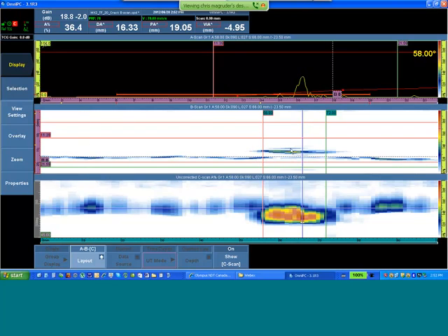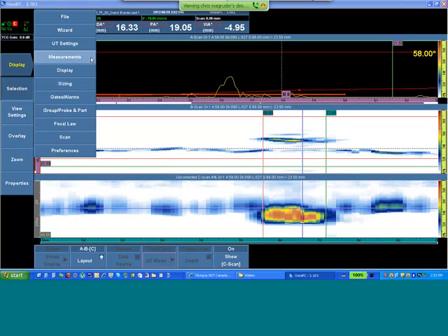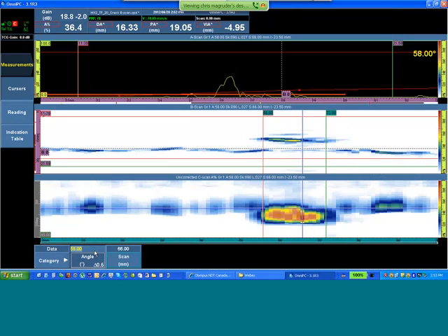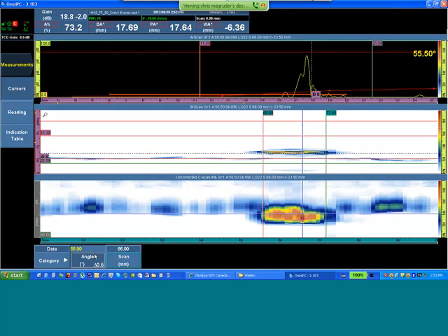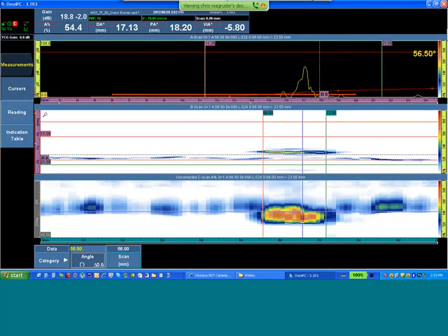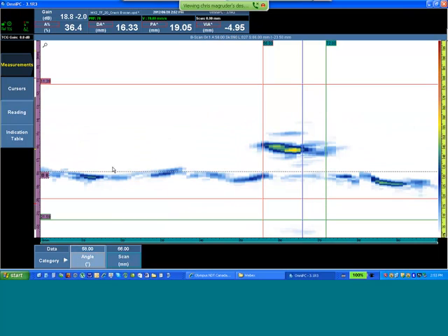So I can see my length sizing and individual different tip facets of the crack from a side view. So menu, measurement, cursors, data, and as I change my angle and roll through the flaw, at this position, we can clearly see the geometry at B0. And we can see the different branches and facets of the crack.